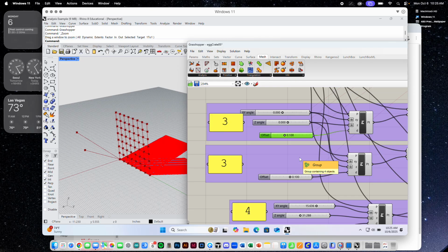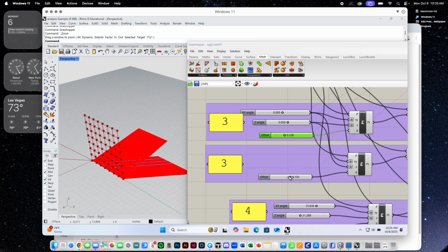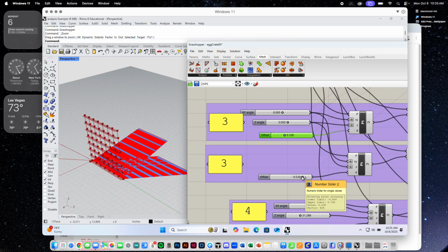Over a couple of seconds for us, but lots of generations for it, it starts to hone in on the most fit solution, based off of the fitness criteria. Over here, as I start to adjust things, I'm getting a readout of the blue, where I'm casting shadows, and the red, where I'm letting unabated direct sunshine through. If I measure the area that's red versus the area that's blue, and I want to minimize the amount of red, then that becomes the goal for the evolutionary solver. That begins to determine the fitness criteria.